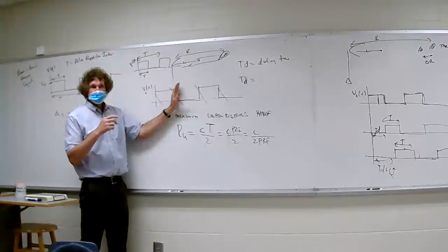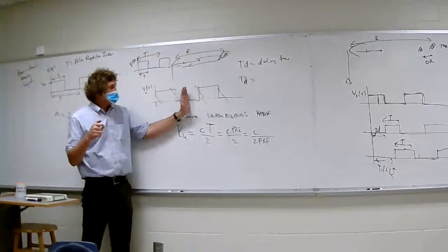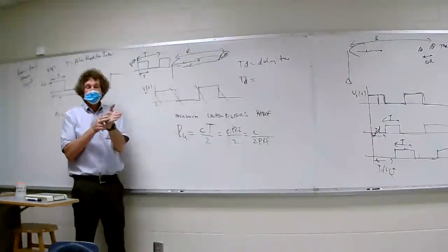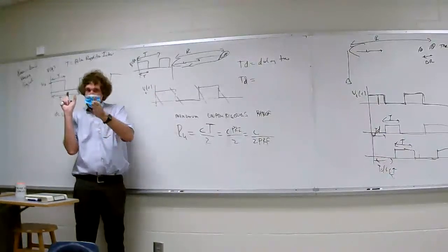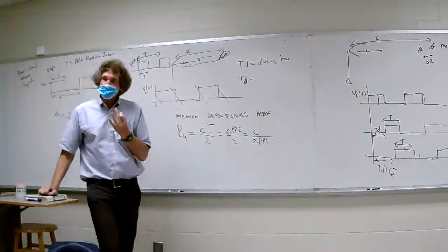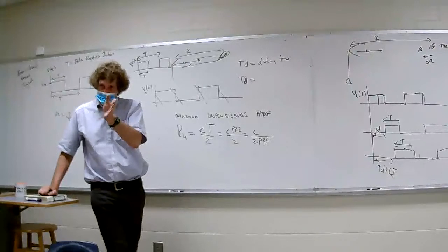You don't care about it, or other radars pick it up. When it starts transmitting, usually this is much longer. Instantly, with a TR switch, it goes from transmit mode to the receiver. There's a thing called a transmit receive unit or a transceiver. It just turns on, off, on, off.